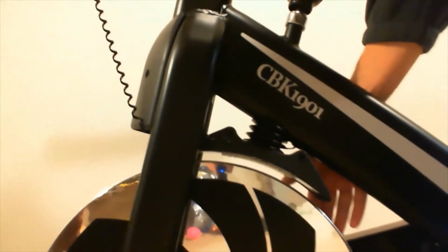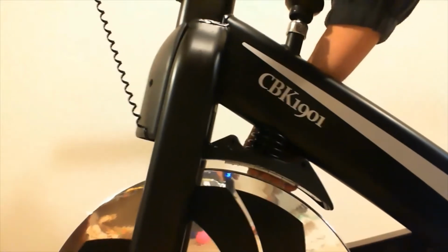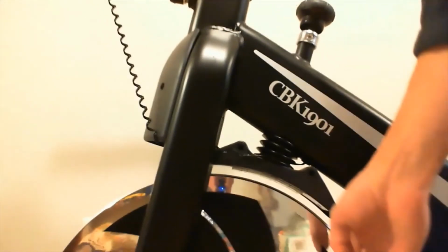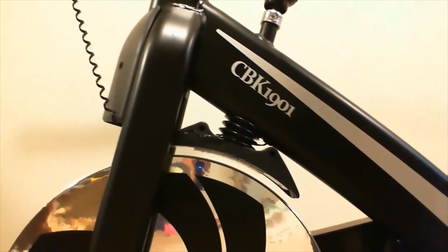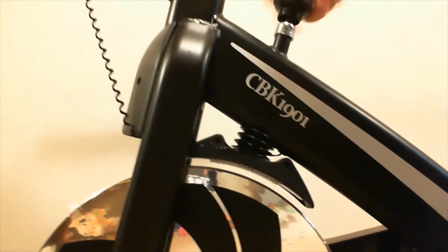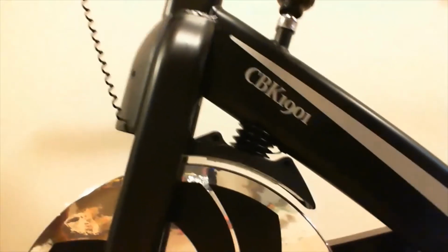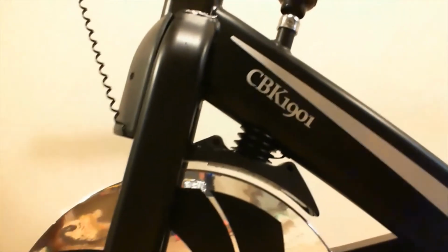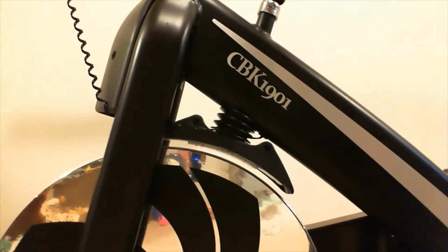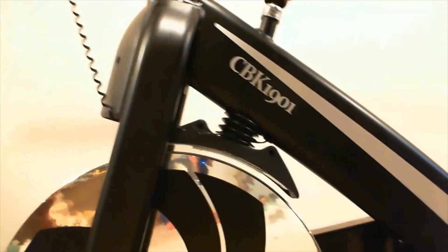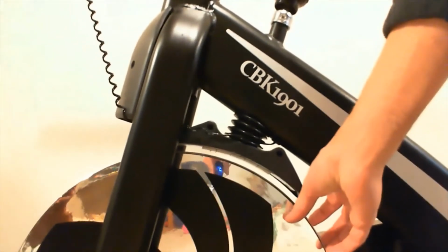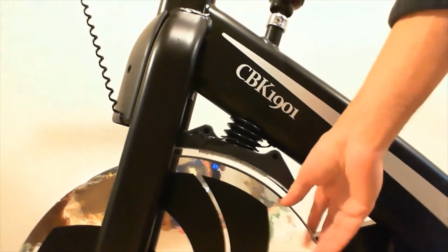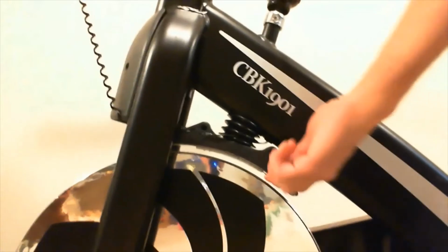The initial magnetic field up here is changing because we have rotation. We feel that as resistance. As I tighten this down, the magnetic field gets closer and closer to the spinning wheel, and it feels that as a stronger and stronger magnetic field. So we get a larger and larger induced voltage, which creates a larger and larger current flowing inside this metallic wheel. And the direction of current flowing inside this wheel acts to oppose the magnetic field.